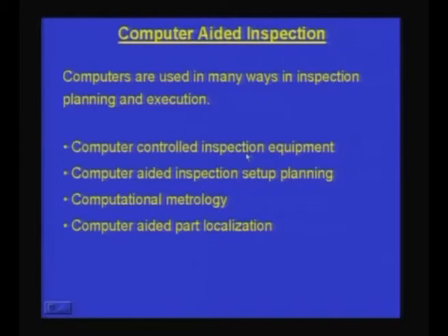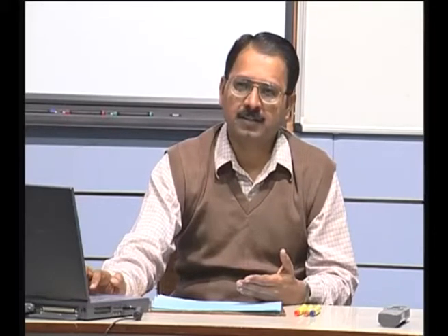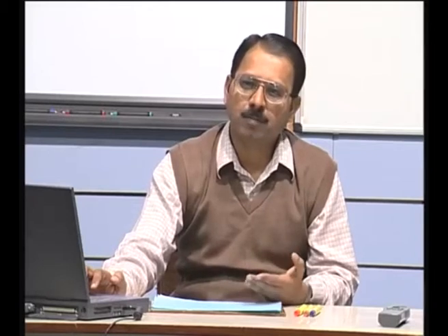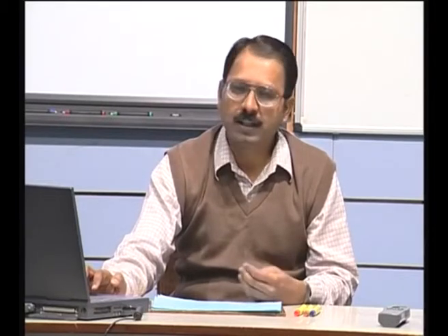One commonly used inspection tool is a coordinate measuring machine, which is a computer controlled machine, or I can have a profile projector which also has an interface with a computer, and it takes the image or geometry of the component which you are trying to inspect and compares it with the original geometry to know what the deviations are. So, a lot of metrology equipment these days have a computer interface or a computer control,